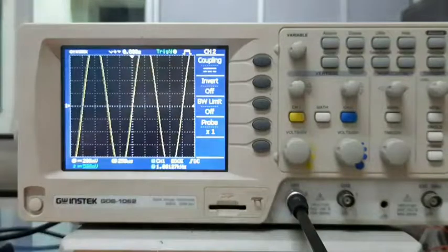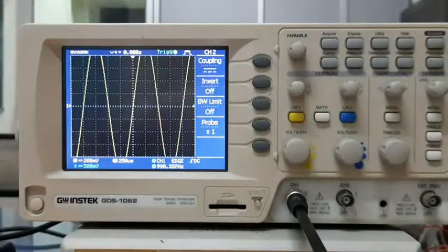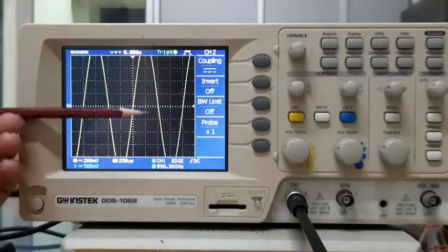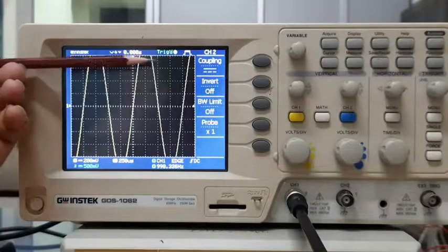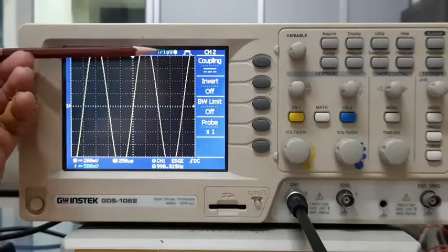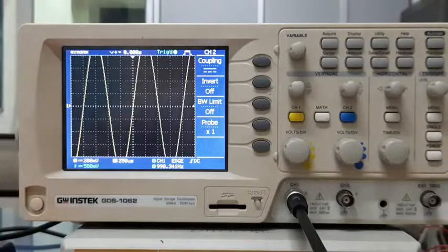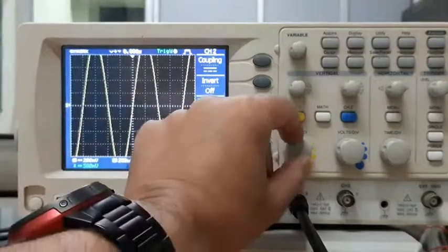So if I change the scale to 200 millivolts, now with 200 millivolts, the display range becomes 0, 200, 400, 600, 800. So maximum on the positive side, it can show 800 millivolts. Similarly on the negative side, and the result is obvious that now my 1 volt peak signal is not fitting in here, right? Okay. So that's how you fiddle with the range.